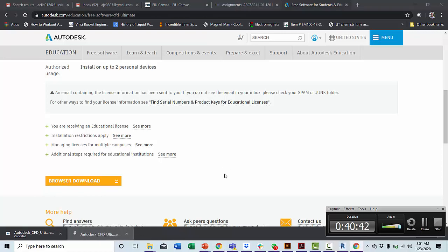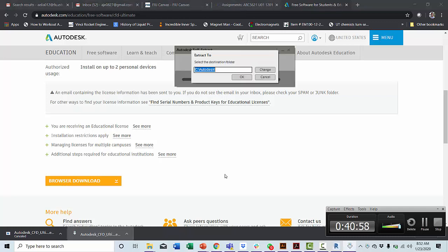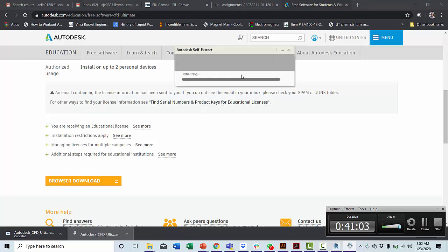What is CFD? The letters stand for computational fluid dynamics. Basically, wind is a fluid that you will analyze on your building. It creates a specific surrounding, a condition box I think it's called in the software, and you start adding different elements in that box. So you will put the direction of the wind, the intensity of the wind, the overall temperature, the overall humidity, and that will give you the results of how the wind is going to behave with that specific mass.